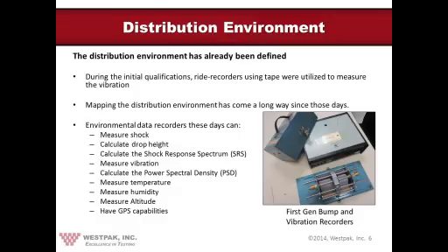Okay, Paul? Absolutely. So how do we know what some of these hazards are and why, and what are their severity, intensity, and durations? Initially, ride and bump recorders were used to gather some of this data. They were mounted to the bed of a truck or a rail car, and a pen recorded the levels on a rolled piece of graph paper. The paper was then evaluated manually, and shock and vibration levels were extrapolated from that. These instruments were clunky, as you can imagine, very labor-intensive and time-consuming in regards to data collection and analysis.